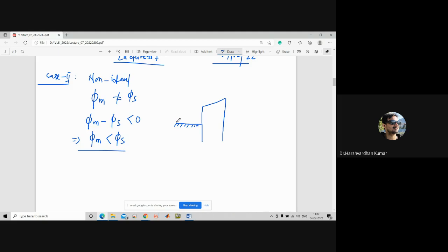The Fermi level of the metal side is represented by EFM. This is metal, this is oxide, and this is the semiconductor, right? The vacuum level will also be tilted, so this is E vacuum, and the direction of the electric field will be like that.